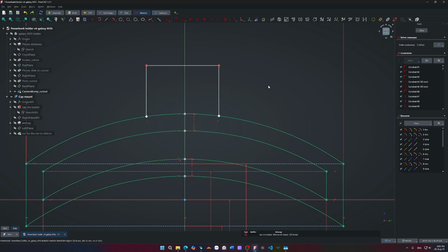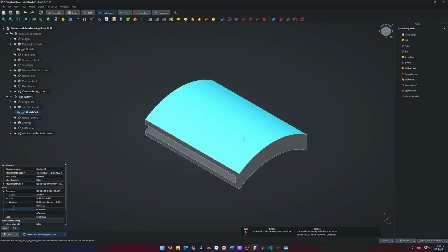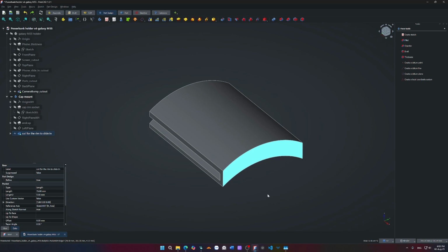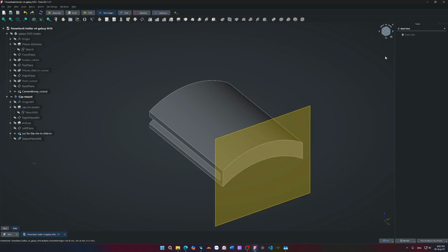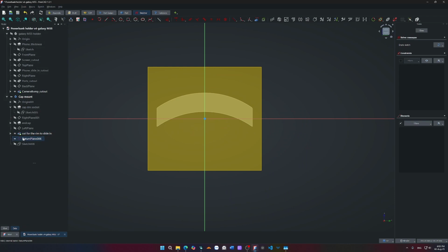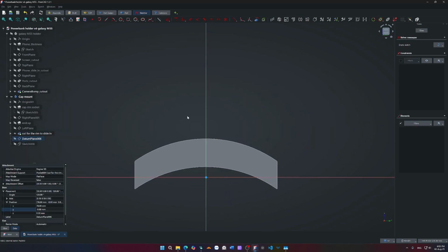One moment please. Okay, I'm gonna close this one. I should have created it from the start, but adding complex geometry like that will require me to basically resketch the entire thing. So now I will create another datum plane. I'm not going to name this plane. I will create another sketch. Turn off visibility. There should be a shortcut for that, to be honest.